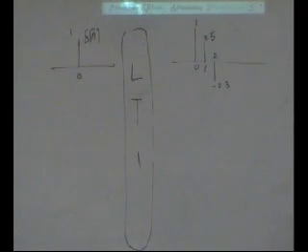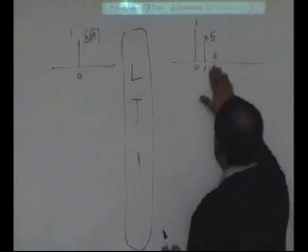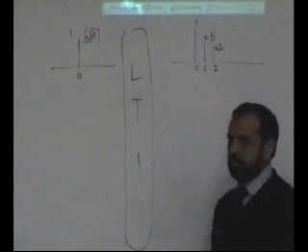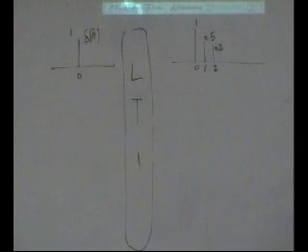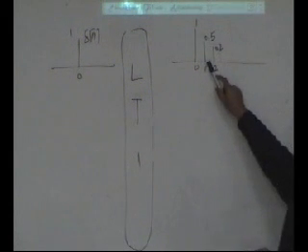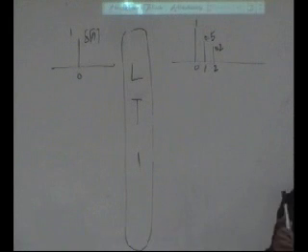An impulse you transmit, and the receiver always gives you 3 paths. Each impulse you transmit results in 3 impulses, because the signal is coming from 3 different paths. One, a direct path, gets the same without any attenuation. A path which is a reflection gives you 0.5 fading and a delay by 1, then 0.2 and a delay by 2.